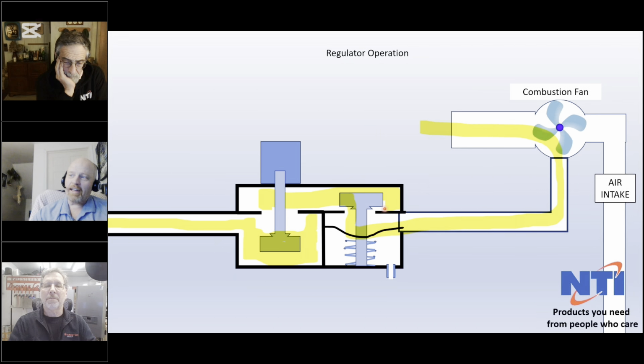And because all the pool chemicals were stored in the same room, the boiler was rotting out from the inside, because effectively it's drawing a bunch of room air now, whereas it previously did not.